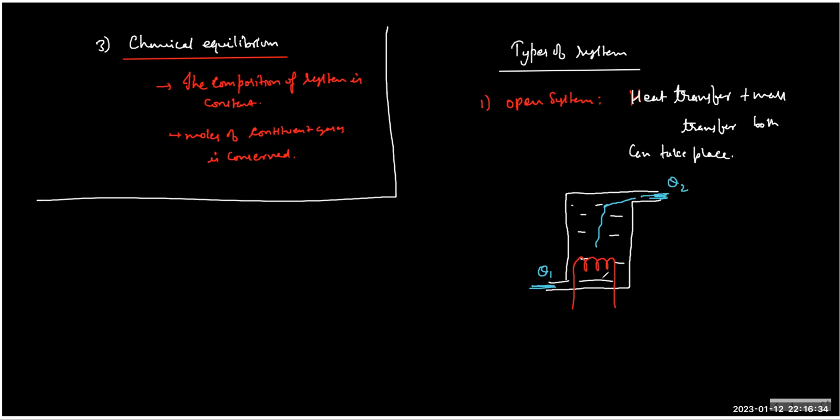So if I think of the geyser as one system, then a geyser represents which system? It represents an open system, right? Because the mass is also coming inside and going outside. The water is mass, right? And it is coming outside with a different temperature. So it is also taking heat from the heater, isn't it?